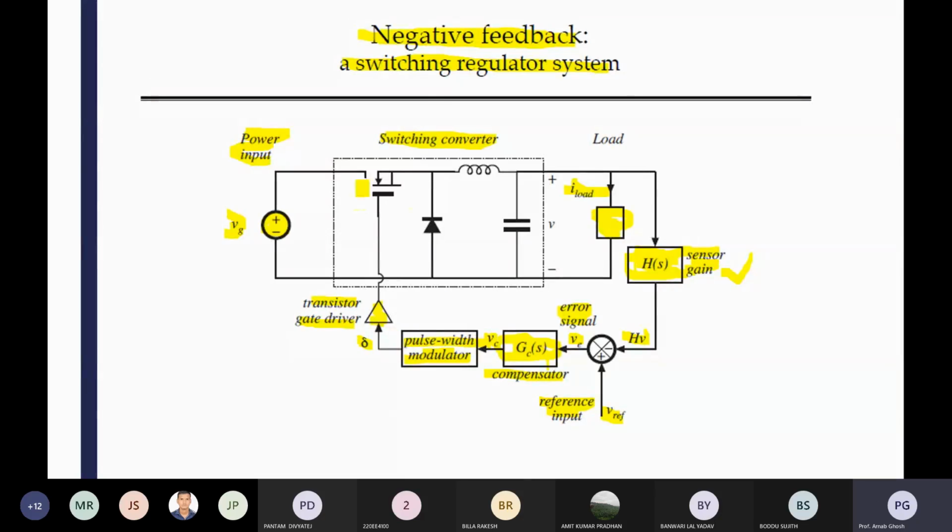But PWM will be there, there will be no problem. So MCT2E normally we are using. Optical isolator, take an example, MCT2E. If the PWM is there, light will be emitted. It is a photosensitive device.